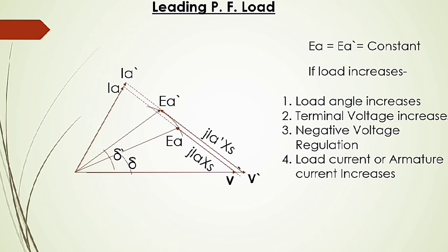So if we increase the load, this is what happens: the load angle increases, terminal voltage increases, negative voltage regulation, and load current increases.